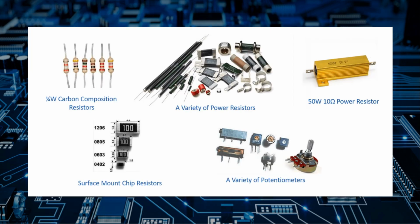When choosing a resistor, it's important to understand the application. Do you need very accurate resistors, ones with a very low tolerance? How does the resistor need to behave with respect to temperature? Does it need to be extremely temperature stable? Some resistors, called thermistors, which we'll learn about in Lesson 4, are specifically designed to correlate their resistance to temperature. They're used in applications for thermostats and other temperature sensing applications. Other resistors are sensitive to light and vary their resistance in proportion to the amount of light striking the device.